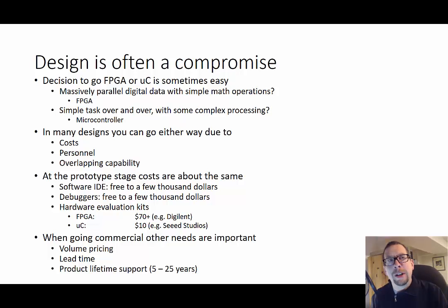And so you want to take a look at, with a PIC microprocessor, has it been around for a while, and is the vendor willing to support it for a long time? Have they stated that development path for you? Or is the chip that you're about to choose slated for obsolescence and is listed on the website as not recommended for new design? Those are things that you want to consider.